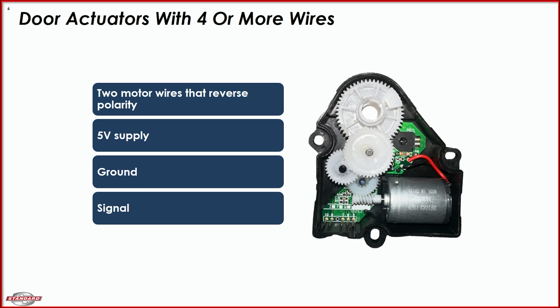They also have a ground wire, which the manufacturer may also call a VREF wire. Unlike the 2-wire actuator, the 4 and 5 wire models have the ability to move with increasing precision and complexity through specific voltage inputs and signal feedback to the climate control module.